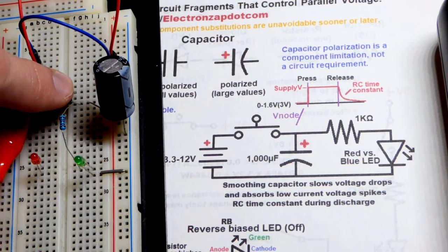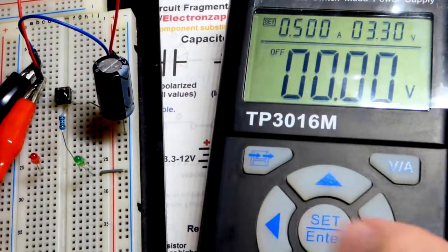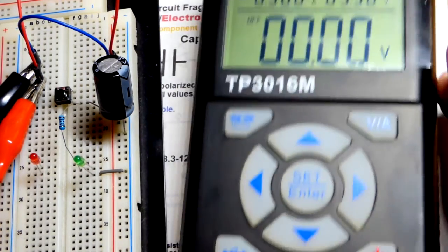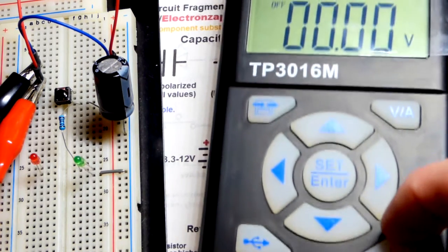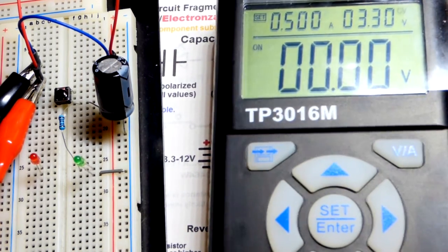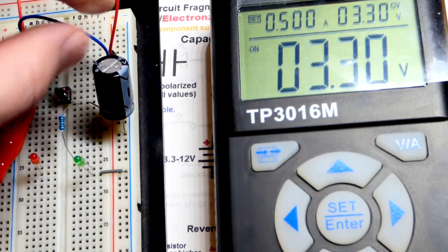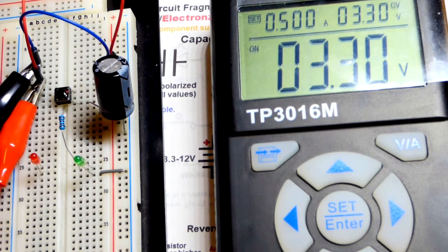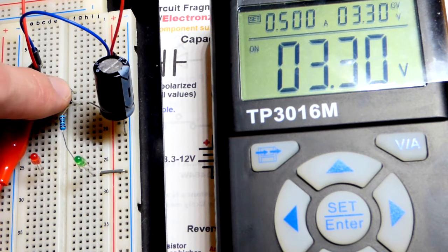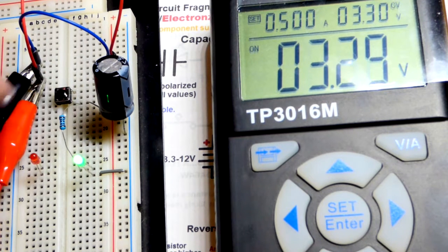So we're going to press the switch, and I have to turn the power supply on first, actually. So there you can see it is off. That is the output. There's an on-off button right there, and so I'll press the on-off button, and now you can see on, and we have the voltage. That is the output that we plugged to the rail, and I clipped the alligator clips to the jumper just like we did before with the other power supply. Now I hold the switch, the LED turns on, the capacitor charged instantly. I release it, you can see that it goes off.